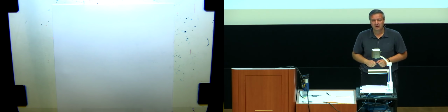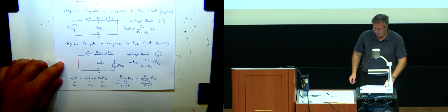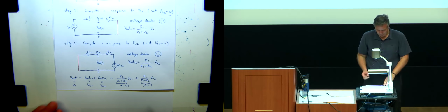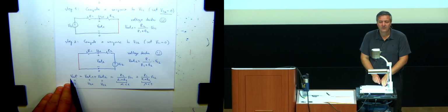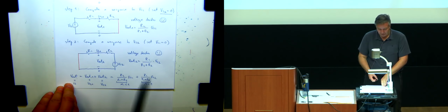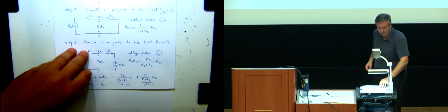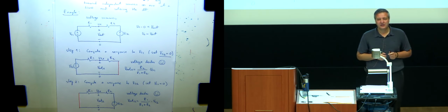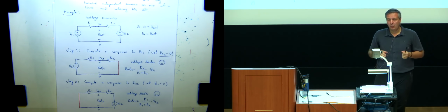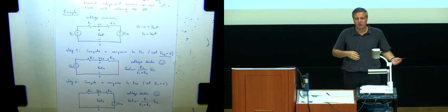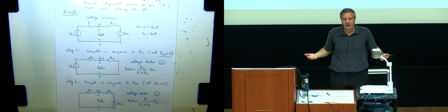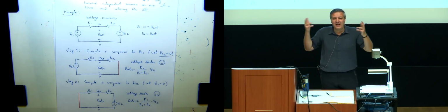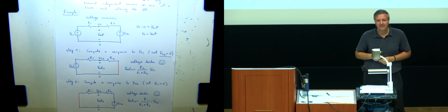We're going to use it. Yes? In that equation, are we assuming all the coefficients for the currents are 0? Oh yeah, great question. Are we assuming that all the current coefficients are 0? Well, are there any current sources in this circuit? No. So all the coefficients related to the response to current sources are 0. In fact, because there are none, even the values of the current sources are 0, because they don't exist.